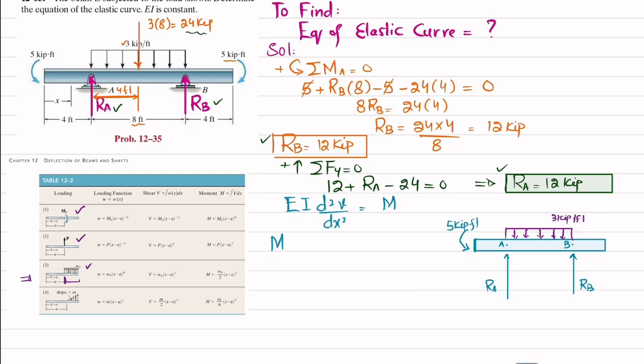So what we will do is bring it till the end and subtract it in this portion, and this load will be upward in order to cancel the effect. So what we have done, we have added this in the downward direction, and in order to cancel its effect, the same distributed load is also added but in the opposite direction, so that these two cancel the effect.